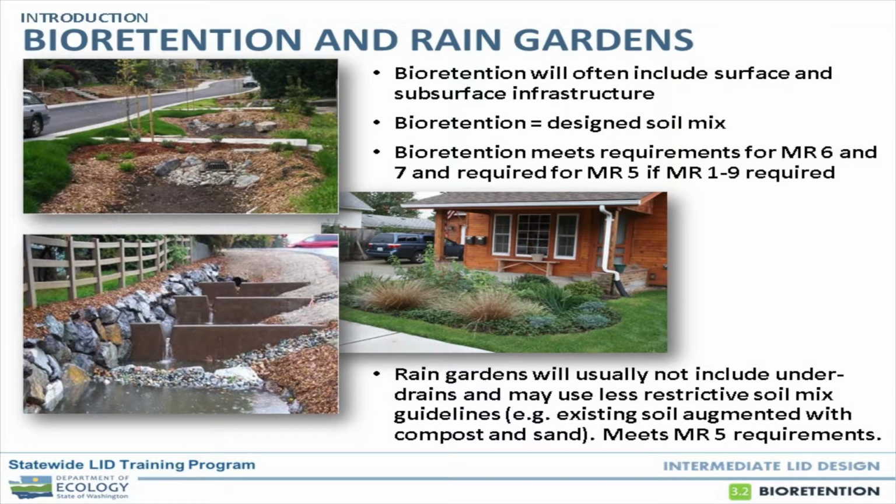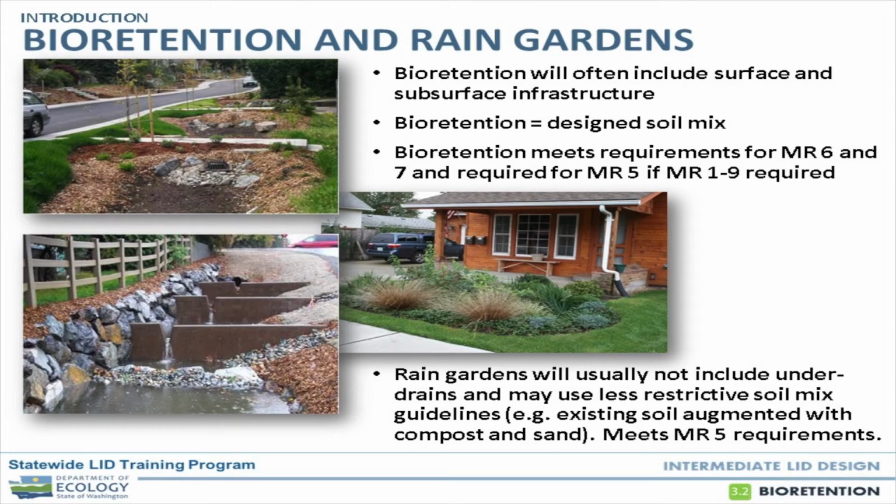Bioretention, it is required that you have a designed media that meets the current specification in the Stormwater Management Manual or equivalent. I'll tell you right now, we'll look at some data, but the current specification for bioretention media, we now can say with high level of confidence that for the first 1, 2, 3 years, perhaps more, flushes phosphorus.